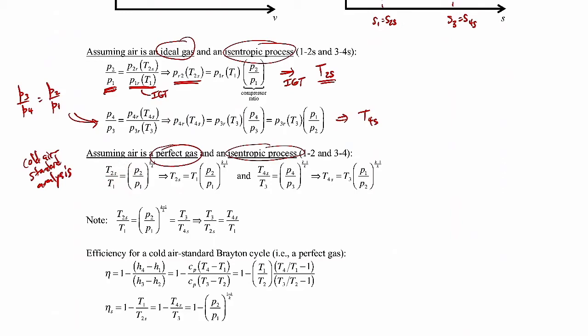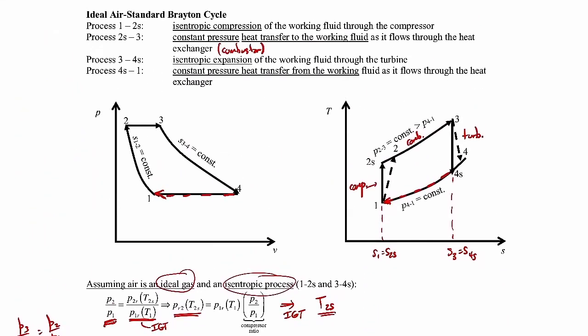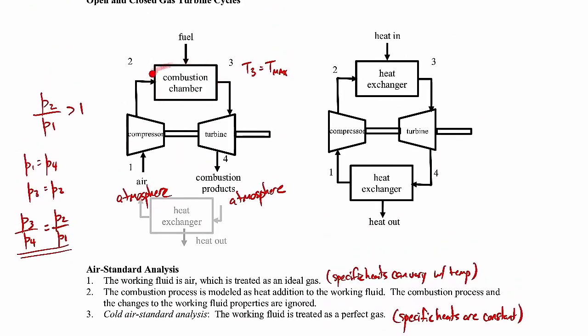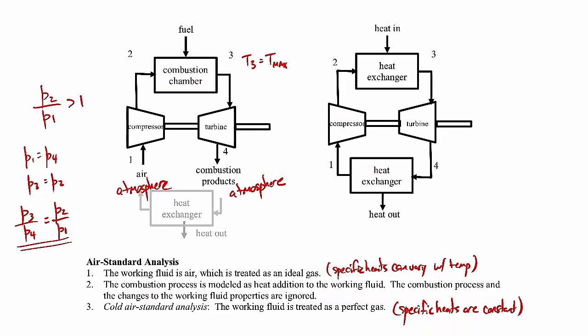Again, this is not the most accurate way to do things because we have large temperature differences, but it's convenient for just qualitative understanding. So that's how you would analyze what's happening across the compressor, across the turbine, and of course through the combustor, we can always apply the first law to see what the heat addition is and how that's related to T2 and T3.